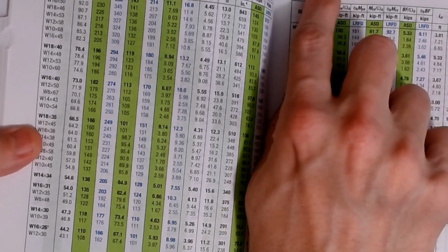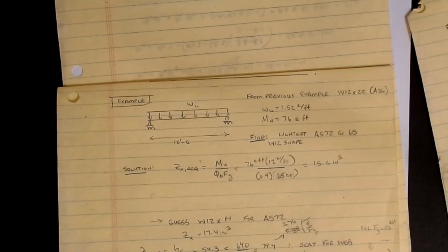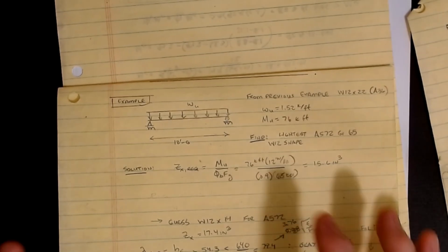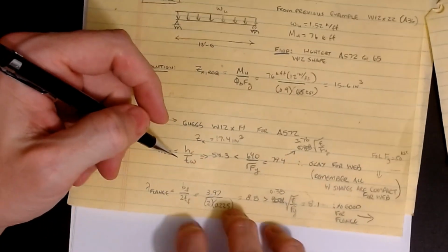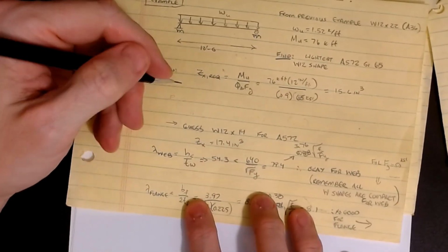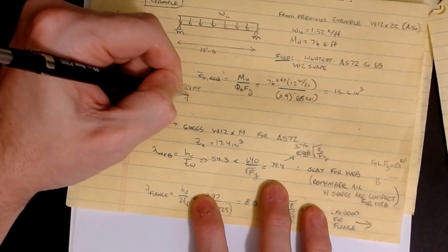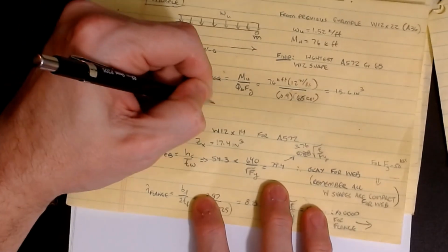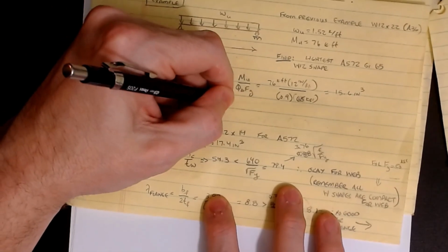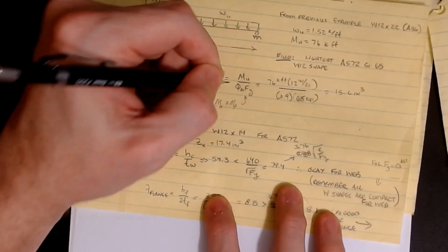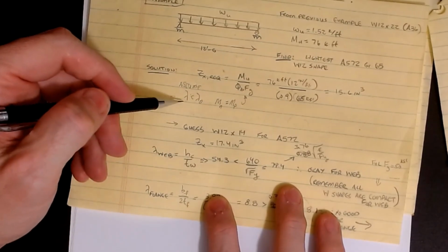Okay, again, we're doing a 50 KSI table. That was up here. But our strength on our problem is 65, so we do need to check, but we're just using a table to get the Zx values. All right, so here's what we're going to look at. We're going to check the web. Again, what we assumed up here was lambda is less than lambda p, which means then that Mn is equal to Mp. That was the assumption that we did. So make sure if you do this as your route on solving a problem, you have to confirm it.